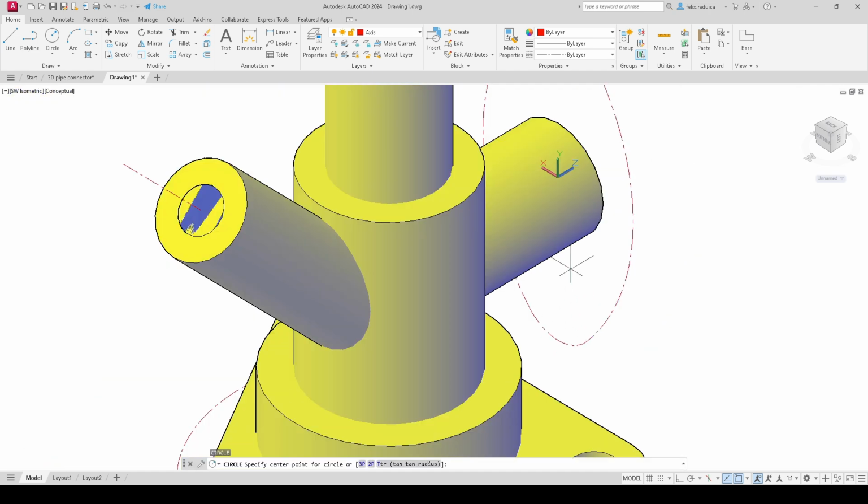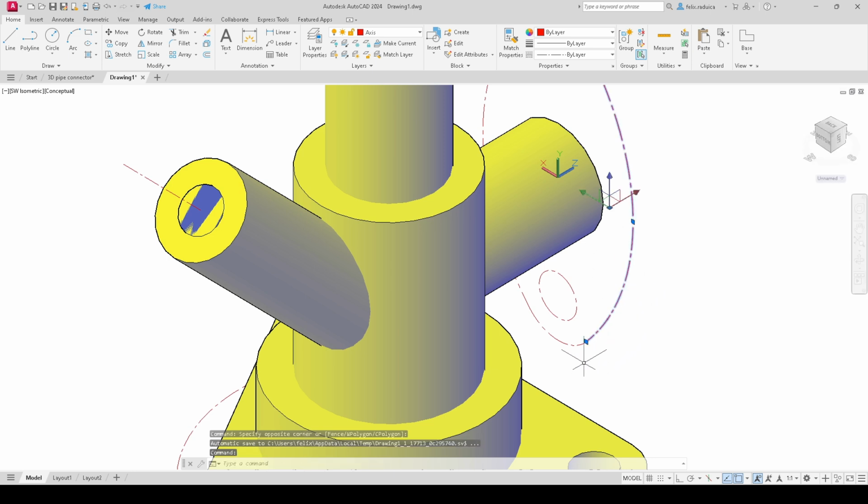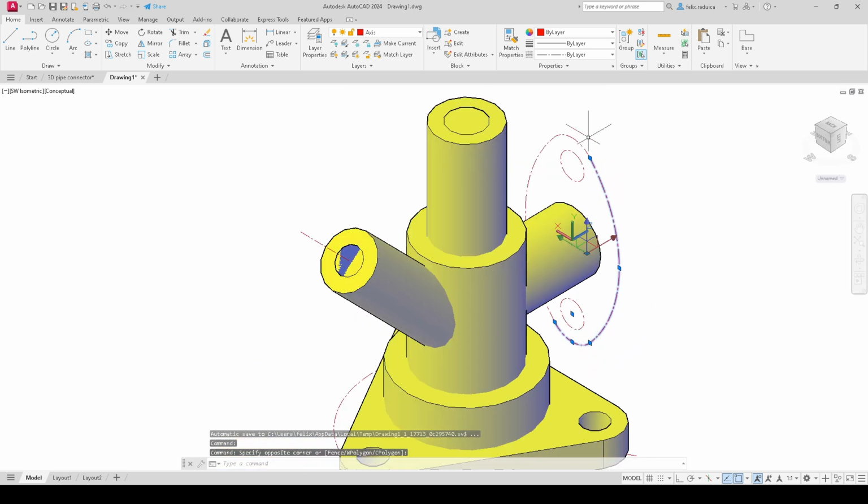and then create another circle which is here. It has the diameter of 10. Right, and now we have to join this to create a closed loop, because we want to extrude this. We create this, we join this together, and to see them better, we'll place them on layer 0, and we have these.